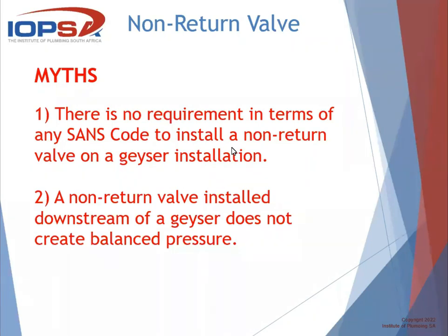Yeah, so Gerrie, sorry to jump in, but I think the key thing is that we're talking about a hot water cylinder now, in terms of putting that non-return valve in. And again, it does protect the cylinder. It is a protection device, but ideally it would be to balance the system. But unfortunately, that sometimes becomes a huge cost in terms of relocating valves and pipework and everything else. So like Richard says, it doesn't balance it. It just protects the cylinder and the PRV. So I think it's one of the key components that some insurers require it, and they're not wrong in doing that, but it doesn't solve the problem.